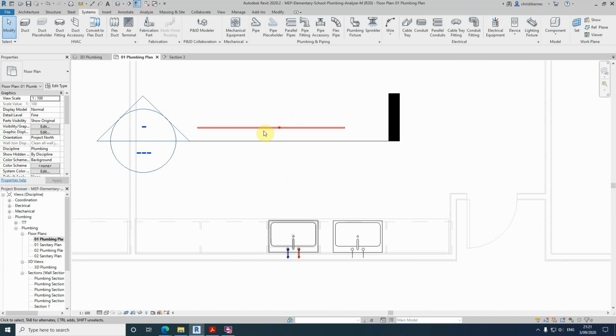Okay, so the next part is sloped piping. When drawing pipes with a slope, it helps to identify the direction that drains to daylight. In other words, when we're working with the drains, the point in the system where it attaches to the exterior drainage system. Then start drawing the pipes from the topmost fixture in the system.